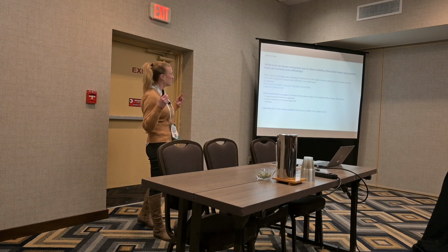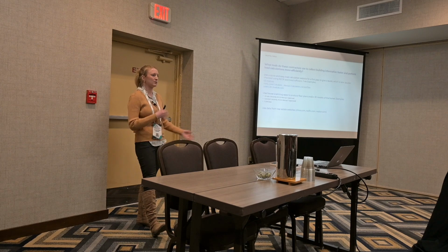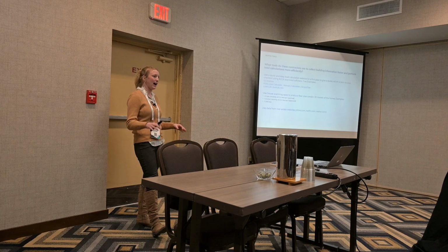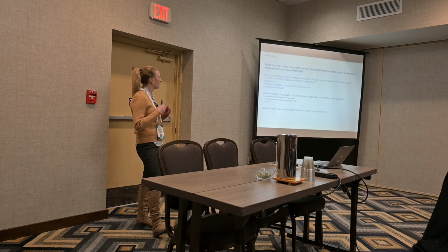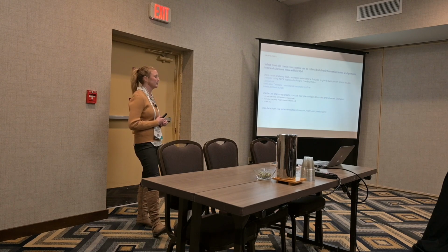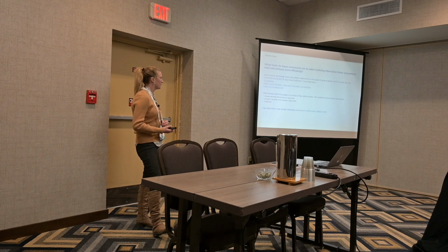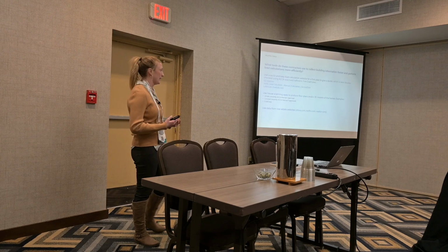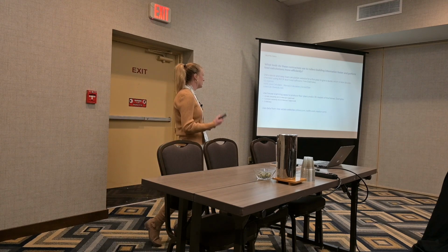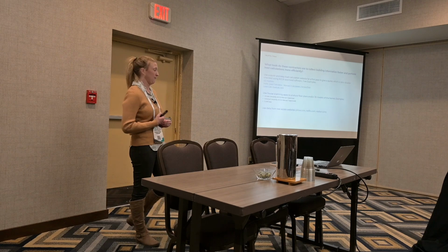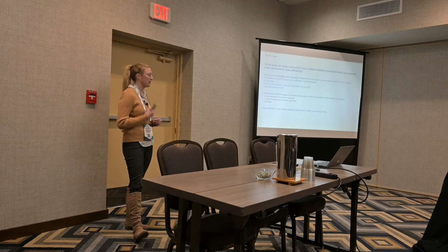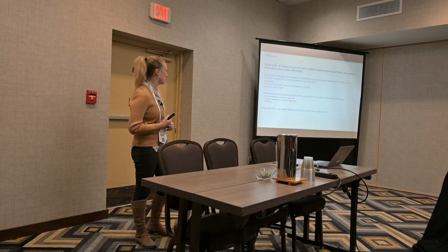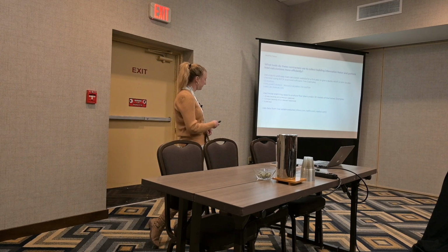So for that, we asked them what helpful tools they use to make this process efficient. For that initial first pass, they are using quick and easy load calculation websites like Easy Heat Loss or loadcalc.net. They also take advantage of house scanning applications like Amply or Conduit to make this process more efficient and faster. They also look up as much information about the house as they can ahead of time on real estate websites such as Zillow and Redfin.